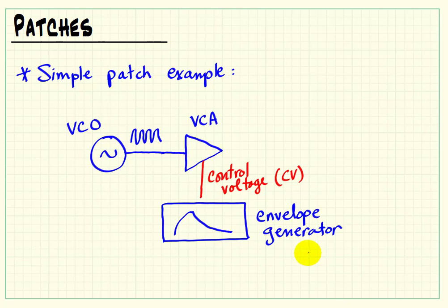So we see that the amplitude would start low, it ramps up to a peak value, and then it starts to decay again. And typically the envelope is created using exponential curves. So with just these three elements, we produce an output that has basically a sinusoidal characteristic, but it's being shaped in terms of its amplitude by that exponential rise and then the exponential decay.